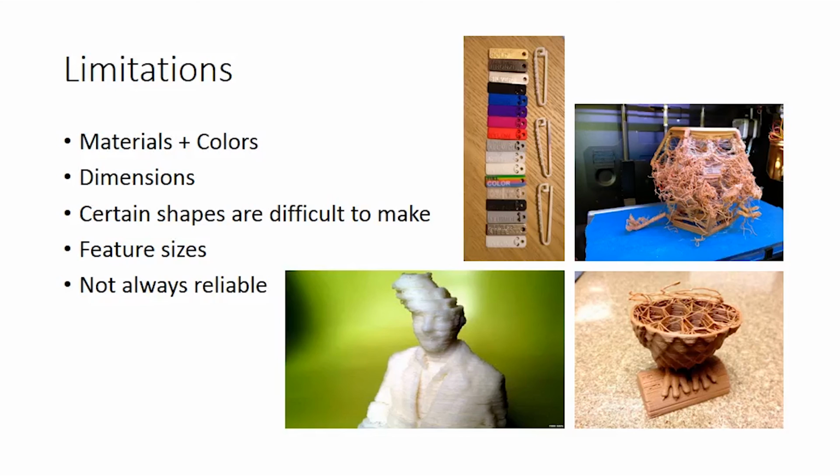Like that model on the upper right there, that's some complicated geometric shape. And with the really thin features like that, it's a bunch of little sticks, basically, that are made into this, I guess it looks like an icosahedron or something. But those thin sticks don't afford much support because the printer has to print up, basically. So it puts layer after layer of material. And with really thin things like that, they could have started drooping. And then once it's drooping, it's trying to print into midair. And then it starts making all that stringy stuff. And then it looked like I got a little bit towards the top when things kind of came back together. But yeah, in the middle.